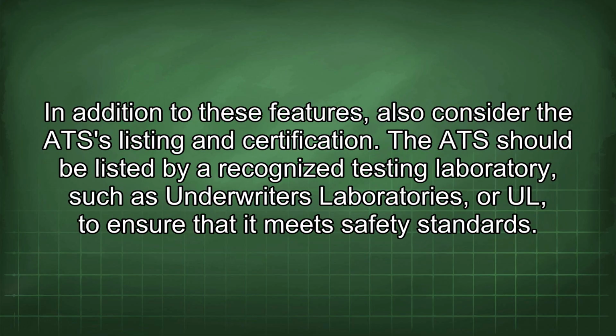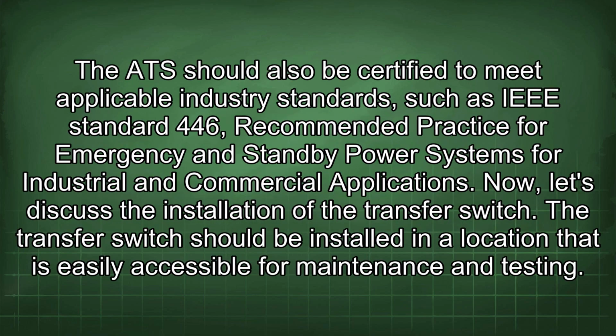In addition to these features, also consider the ATS listing and certification. The ATS should be listed by a recognized testing laboratory such as Underwriters Laboratories or UL to ensure that it meets safety standards. The ATS should also be certified to meet applicable industry standards such as IEEE Standard 446, recommended practice for emergency and standby power systems for industrial and commercial applications.